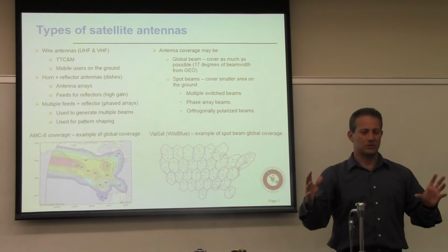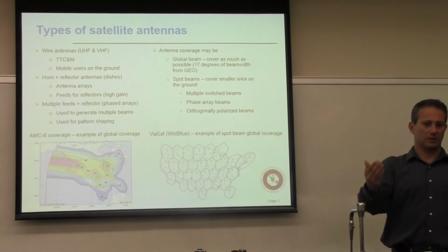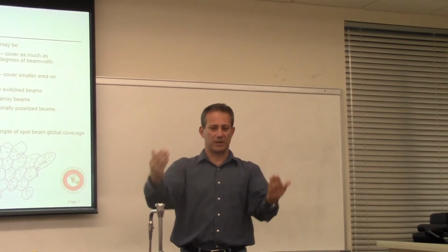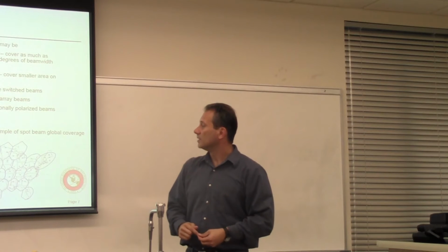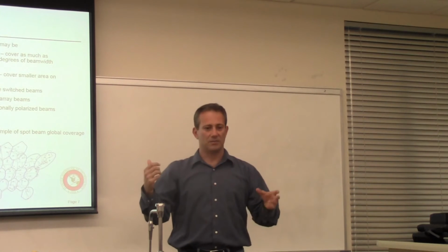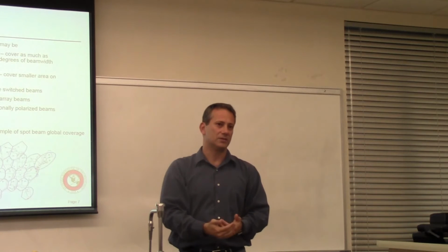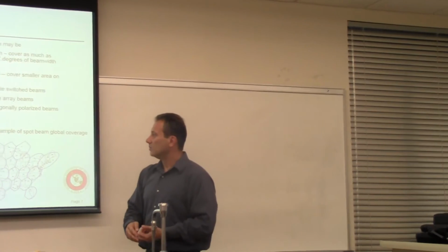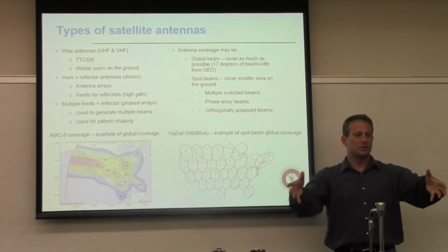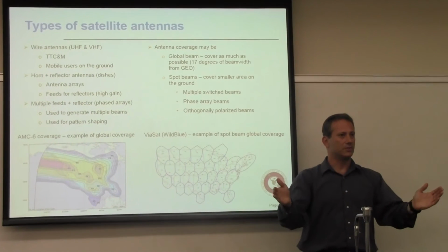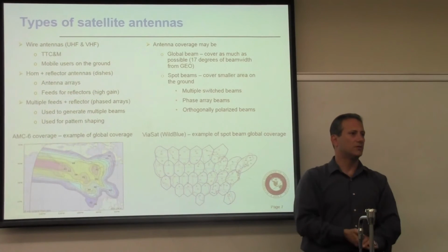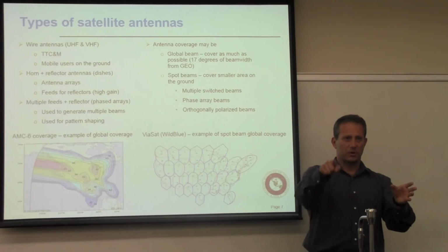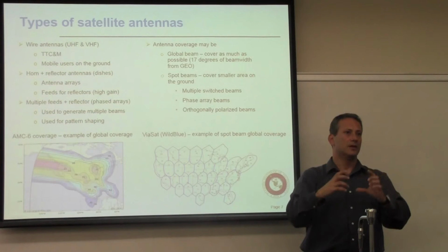And although we look at those dish antennas and we assume that it's all ideal, and that's a parabolic dish or whatever is the surface there, you saw the last time that design of that reflecting surface is a very precise task. And the reason for that is if you go with some regular geometric structure, your beam ends up being spherical. And that would be okay if you're trying to put a spot beam on the ground that is spherical as well. And sometimes we do that.